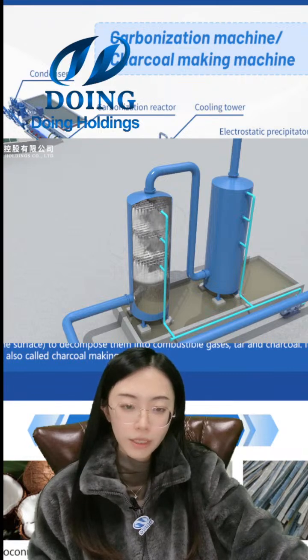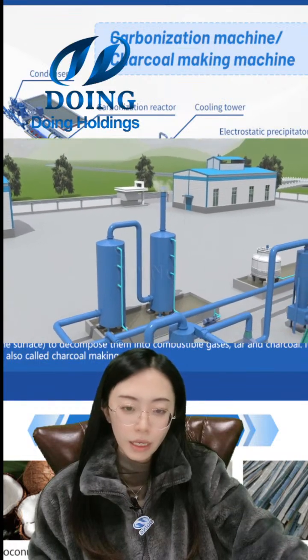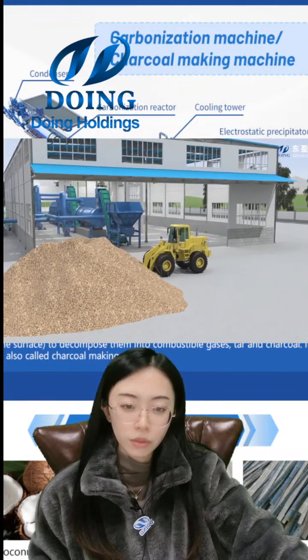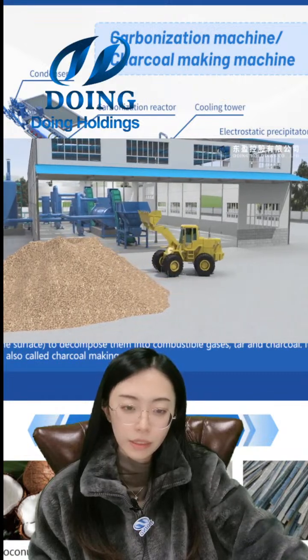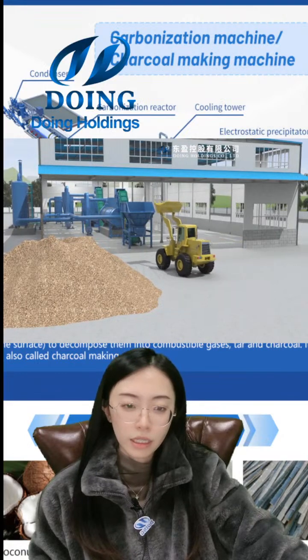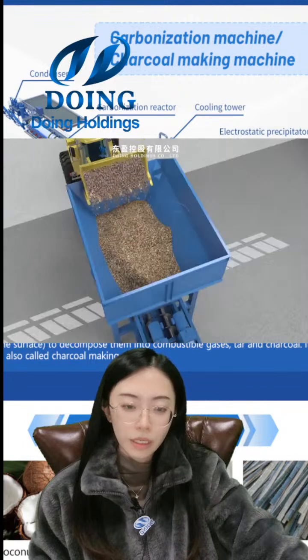The normal temperature of the carbonization furnace is 40 to 60 degrees. The standard for the raw material is that we also need to lower the moisture to 15%, and it's better to crush the raw material smaller than 3 centimeters.